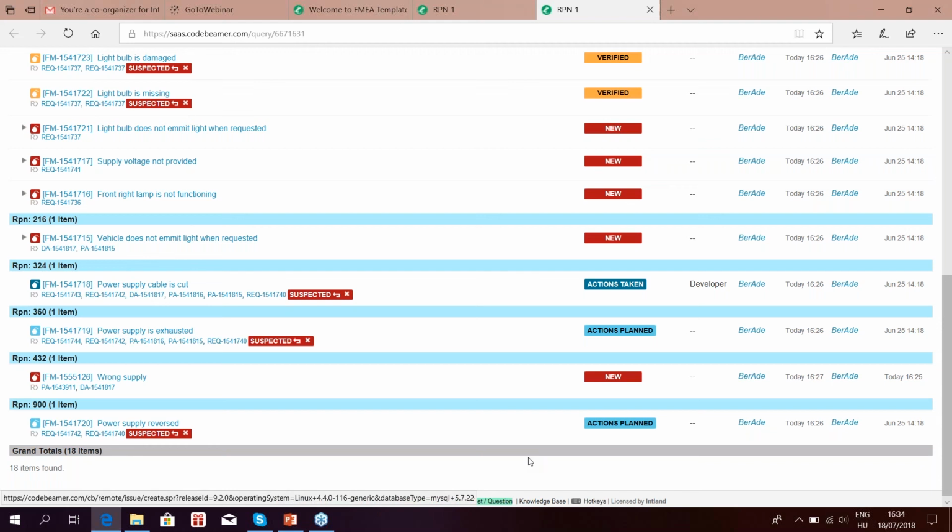Okay, so system FMEA, as a system, normally integrates software and hardware. So you can say that if you are developing an item, then you start the analysis from system level. For example, you can start with listing the safety goals with ASILs, and you will finish it, let's say, on software architecture level, or on component level from the hardware.